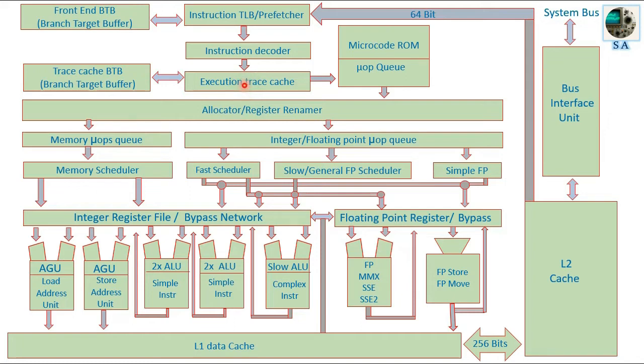In case of more complex instructions, which are normally decoded into a larger number of micro instructions, the trace cache gets support from the microcode ROM, which is a memory storing micro instruction programs. These, we can say, are defined digital words for every instruction to drive the control signals.